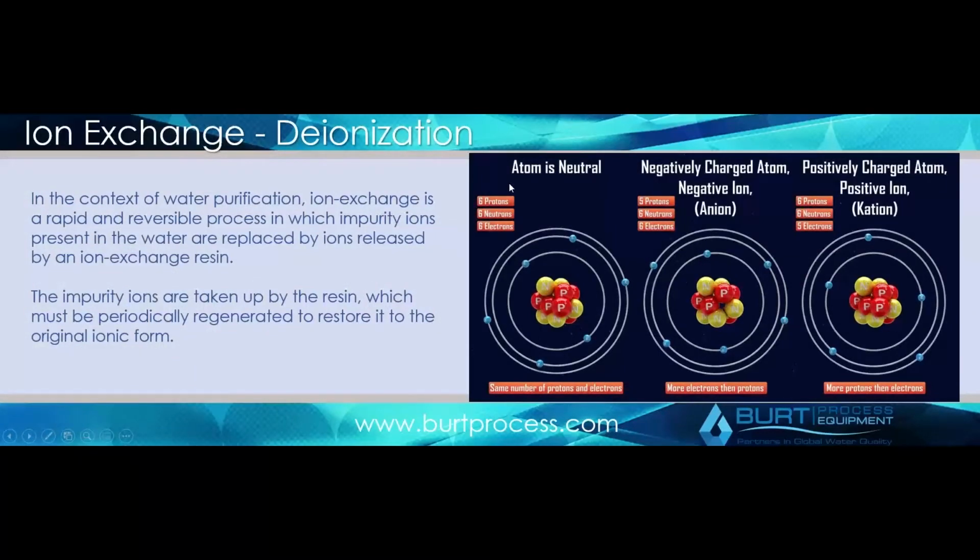We've talked a lot about RO systems in general, but now the next big one that comes up very often is ion exchange. Ion exchange is very different from RO systems, and ROs are a mechanical filter process. You're basically trying to remove all the dissolved solids in the system through a mechanical filtration process.